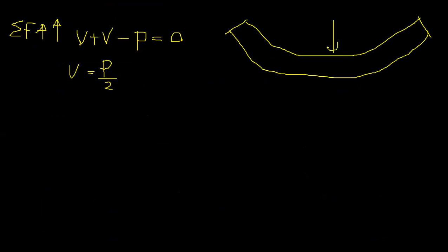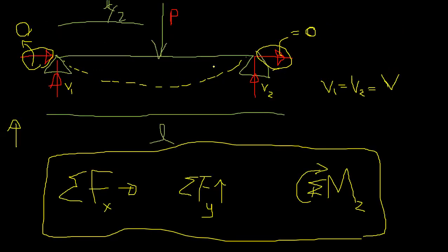For this kind of loading, we need to know that bending moment. At the end, they are going to transfer it to the support. That's the transferring mechanism. Even if it has a shear force, it can transfer it to this support, right? Because it can take shear, but it cannot transfer bending moment to this support.